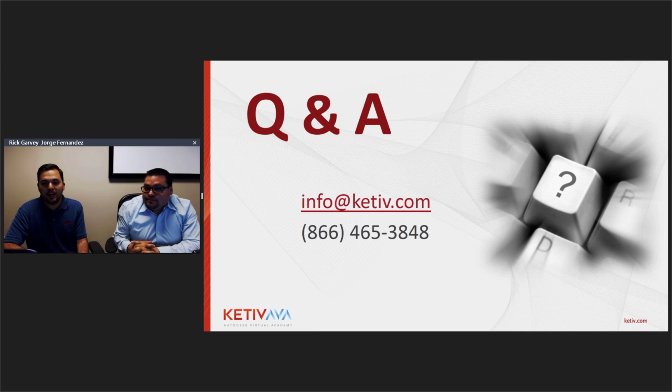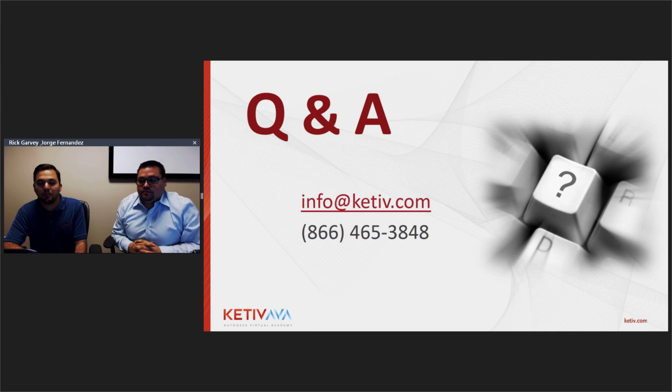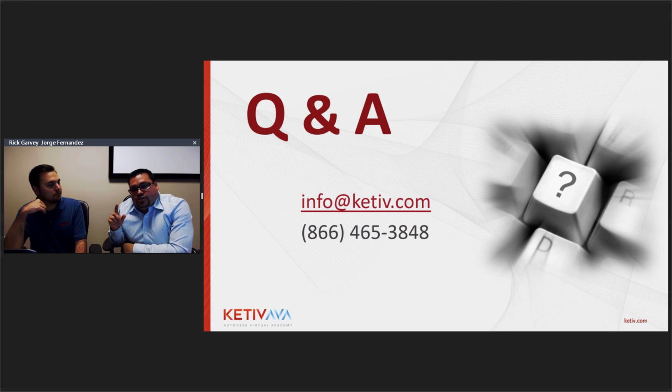Yeah, thanks, Jorge. We got a couple of questions here. The first one is from Brian. He asks, how much of the Inventor component can be adjusted in Revit? Size, parameter information, etc. That's a great question. There is a video that I can send you after this where you can simply say which parameters or dimensions you want to choose and have them modifiable in Revit. Is that a word, modifiable? I think so. You can prep the model so that they get exported, and then you just change that parameter or that dimension in Revit.